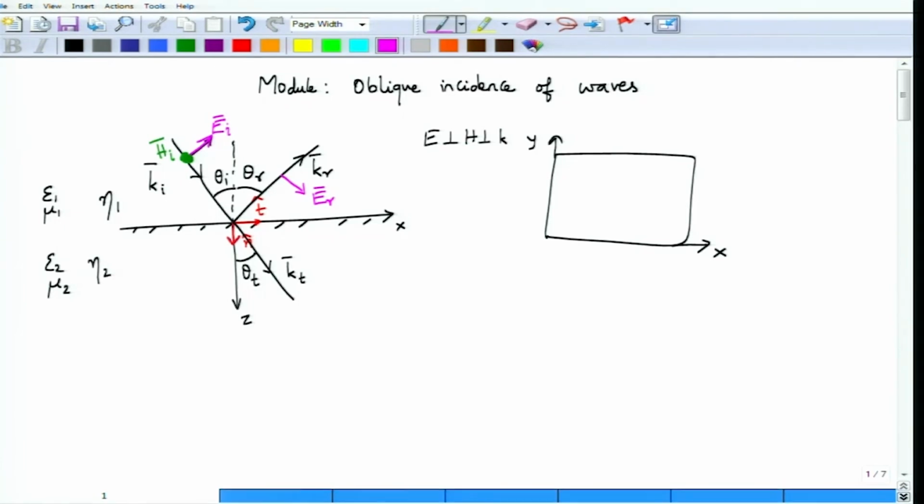If the assumed direction is correct, then the current will come out to be positive. If not, the current will come out to be negative, in which case you can simply change the direction of the current. So very similar thing is happening. Don't particularly worry about how to draw this Ei or this Er. The equations themselves will tell you whether this Er should be reversed or kept in the same way. This is just convention.